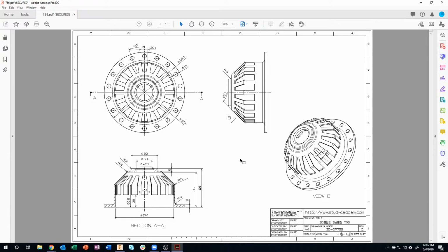And I looked at this one, I said, okay, how would I approach this? It's not overly complicated. We're going to probably do a side profile and revolve it. This is my guess. And then I'm probably going to have to create these little air vents or whatever they're called. But you'll notice that they're slightly tapered. In fact, it's kind of hard to see right here. It looks like they're at a 7-degree taper. So I'm going to have to figure out how are we going to go about doing that. And then obviously I would probably pattern. Let the software do the hard work here.